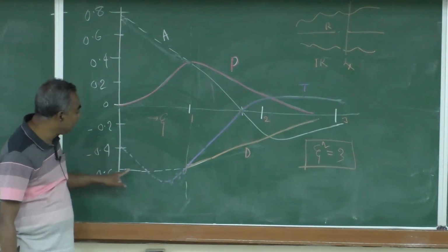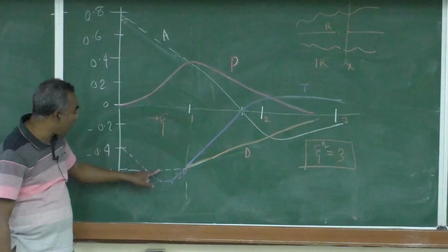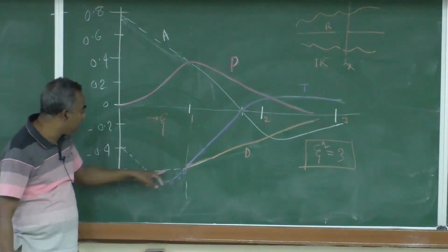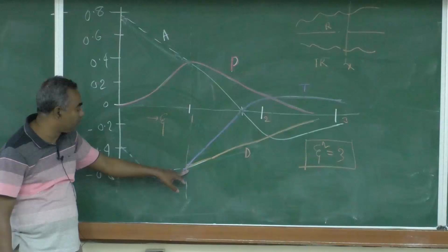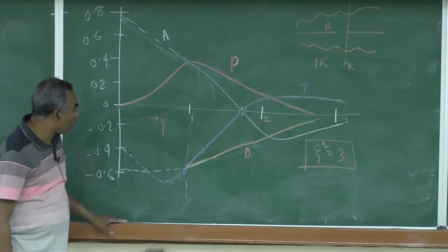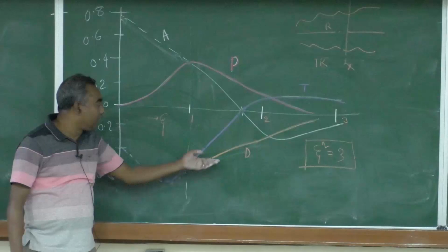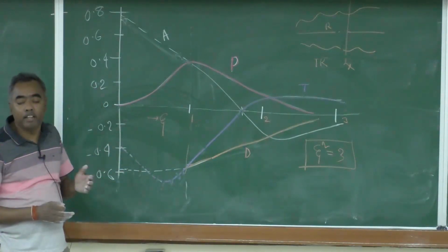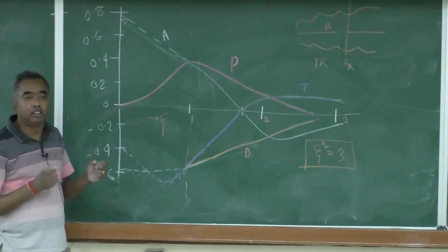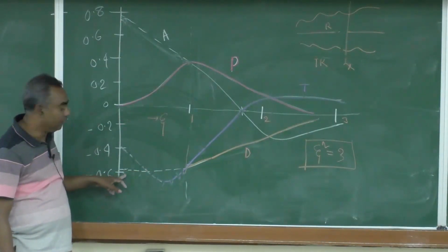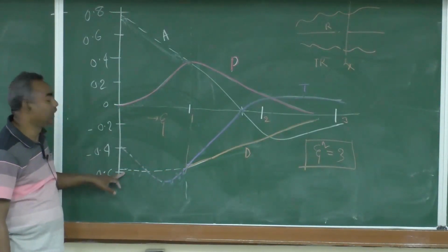That is what this particular line shows. This has been just extrapolated from this line, as per the argument that since near the central line of the wake turbulence is well mixed, the dissipation should increase, that means it should increase like this.